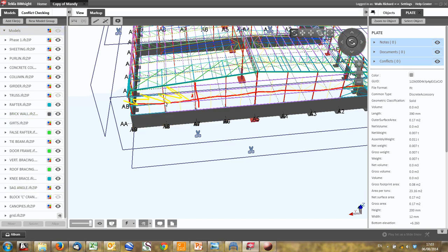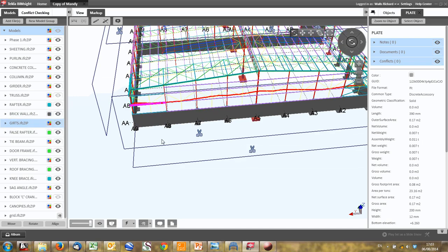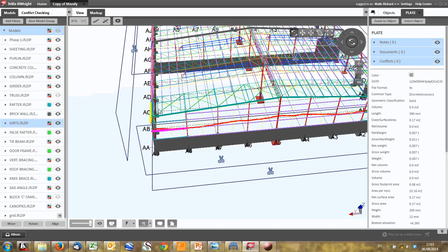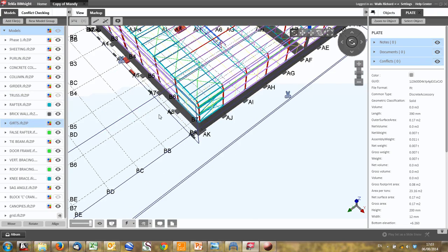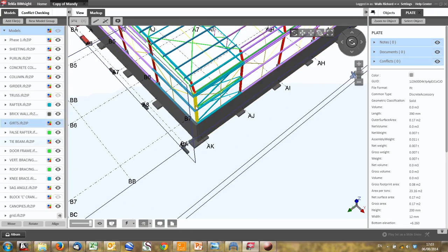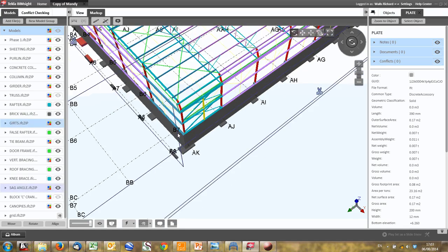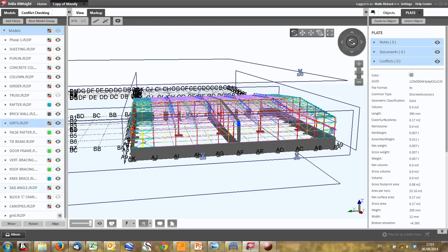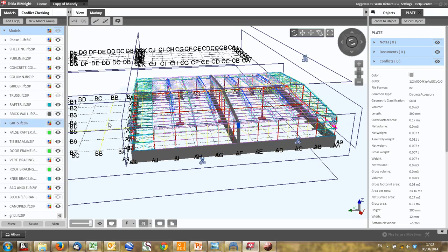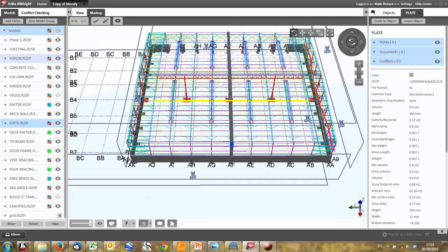If it's a statically indeterminate structure on top, you won't have it with fixities. Obviously, if this is, it might attract a bit more load to the center. But roughly, you can actually calculate that reaction simply by a quarter of this face or an eighth of this face. Apply it all at that point, and you can get that load straight away. But remember, once again, that's only for this face. Whereas if you have suction pressure acting at the same time on this face, that will pull this, and you'll have a load from that same area this side. If you only have one brace bay, let's say you only have this brace bay or this brace bay, you need to add pressures from both sides, as I keep emphasizing.